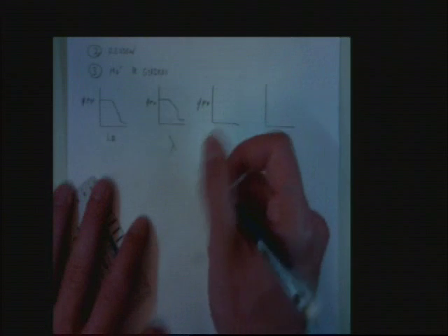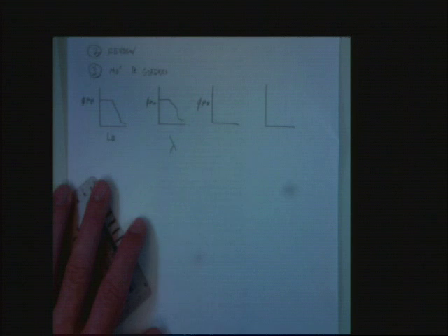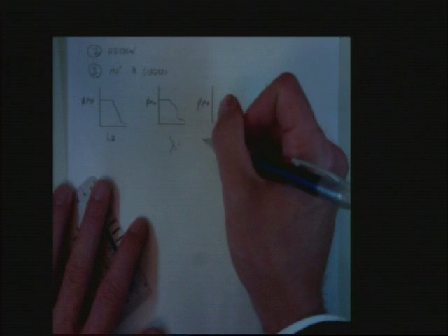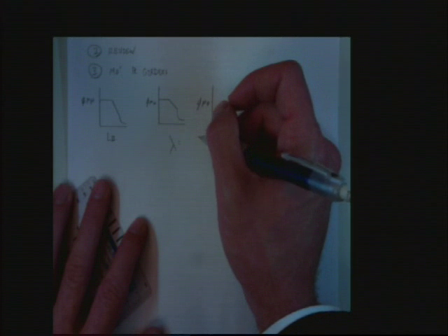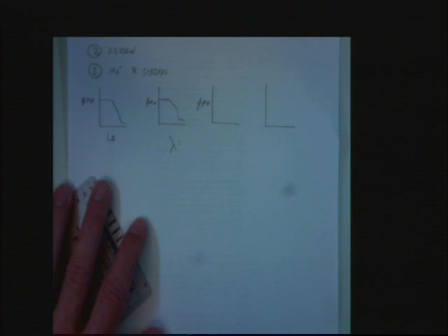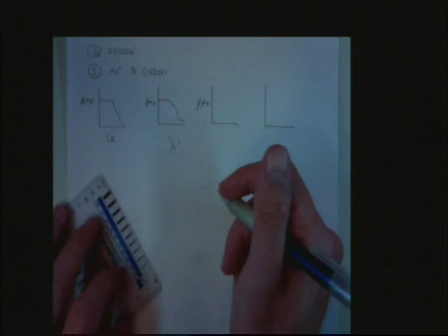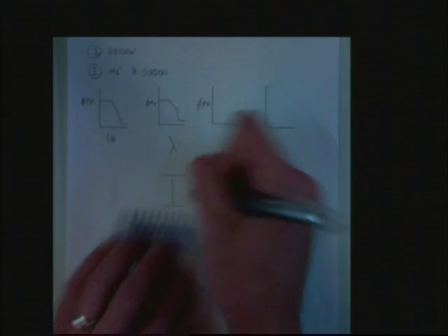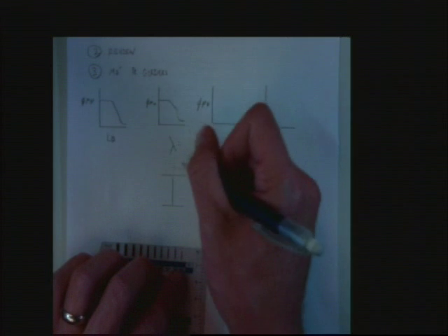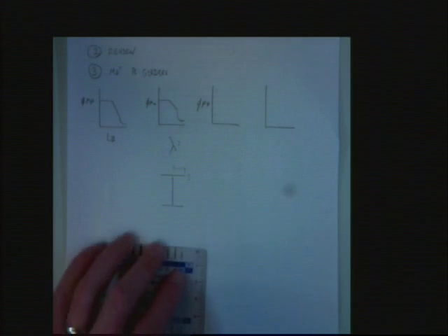That's exactly right. And we'll say it's the one for the flanges. Do you remember what the gamma means for the flanges? What's the equation? It's important. So flange. What would we compare in a flange? What is the critical aspect of a flange? We talk about it getting slender. Thickness. And what's the other one? The width. And usually, typically, when we think of a W shape, truly, we're thinking of this width versus this thickness. You with me?